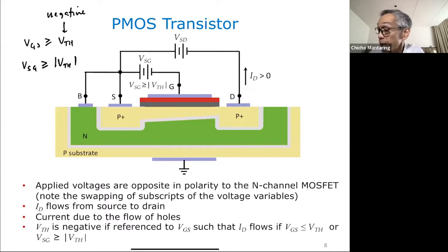Okay, notice that from P to N, it will still be reverse biased, because this is negative. This is negative connected to the P, my positive connected to my N. So this is still reverse biased. This is still unbiased because my bulk and my source are connected. So I still get my depletion region here. Meron pa rin akong depletion region rito.